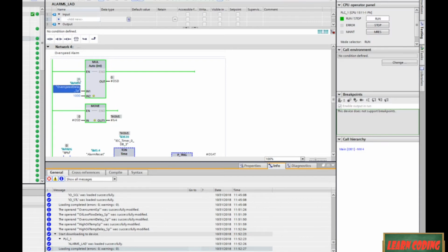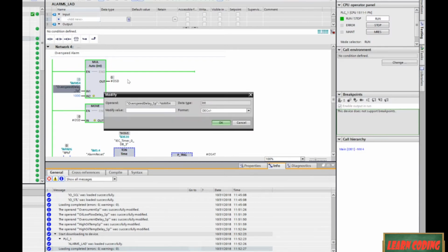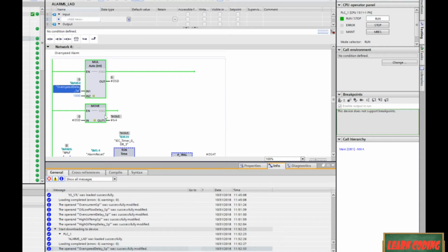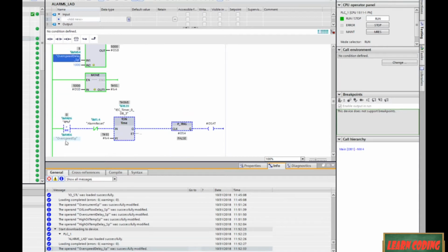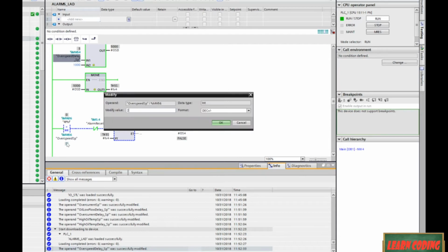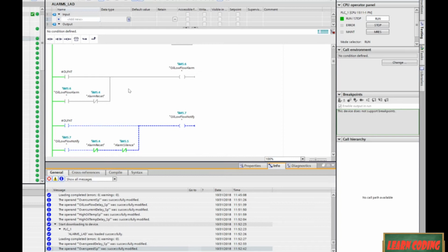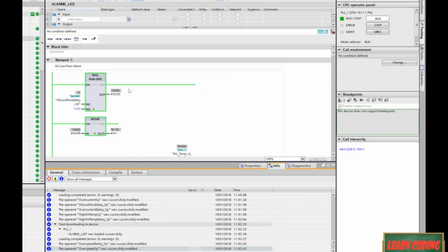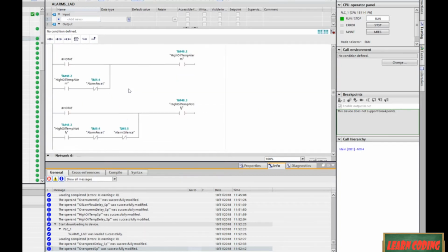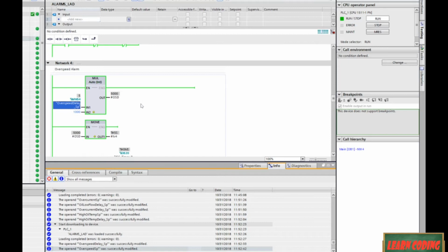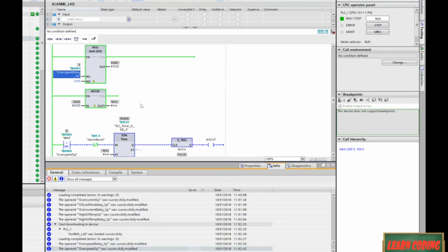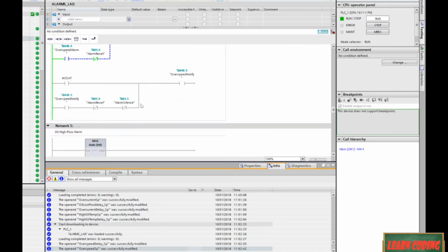Okay, so our over speed delay will be 5 seconds, and for the speed, let's call it maybe 200 RPMs. Let's make sure I didn't lose anything else when I loaded this thing up. Yeah, okay, we didn't. So we've got our over speed looking good.